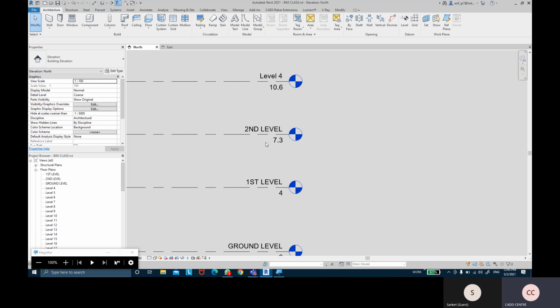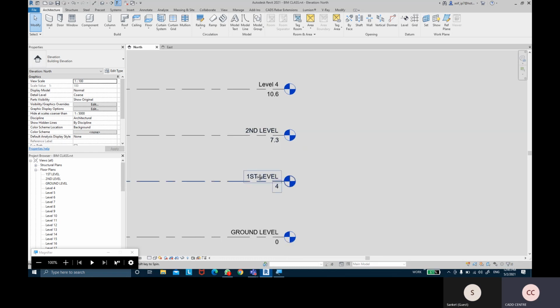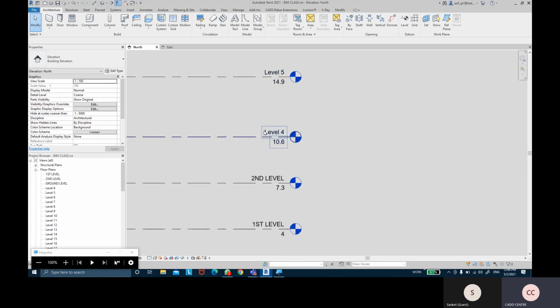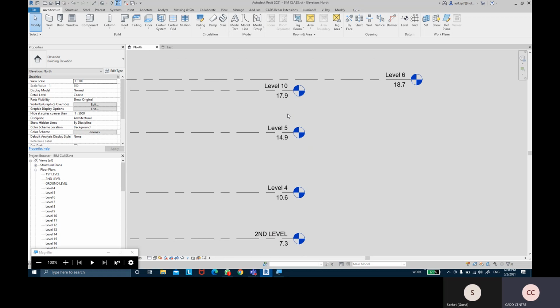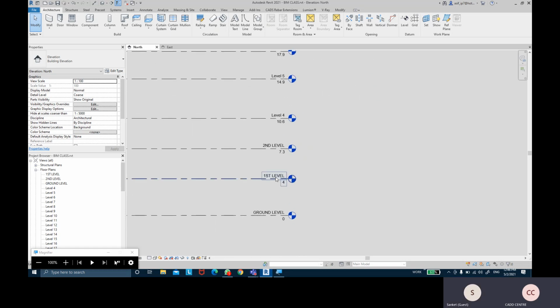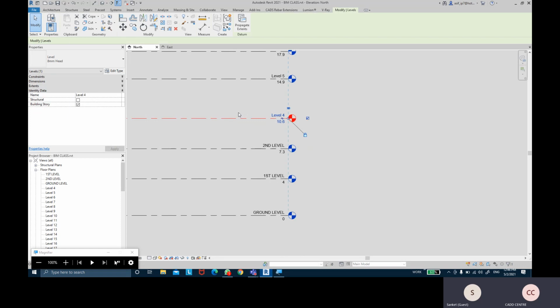Even if I have given a sequence, like second floor or third floor, it will not continue that sequence; you have to name that manually. It will always name them as level 5, level 2, level 3, level 4, like that. So now if we take an offset, say from the second level, even if we take it above, the name will be the next one in the sequence. So we have named it till 22, so the next level will take 23, 24, whatever that number was. It would not rename it.